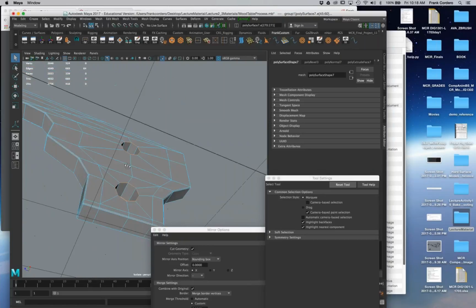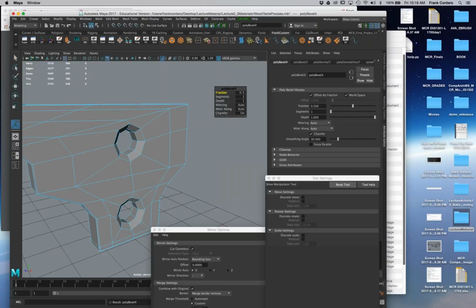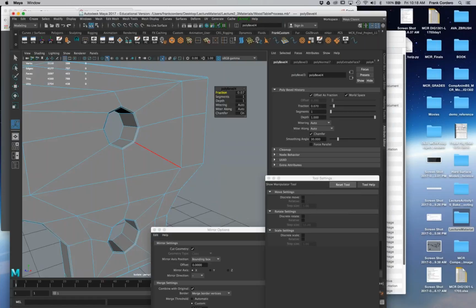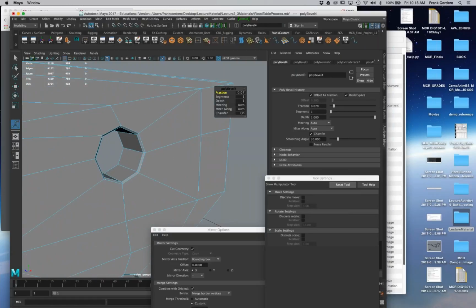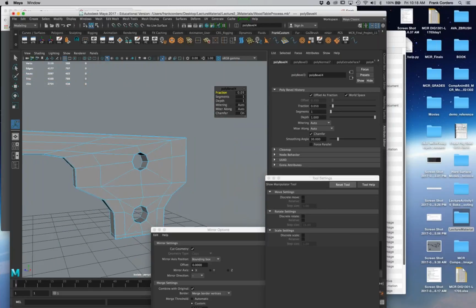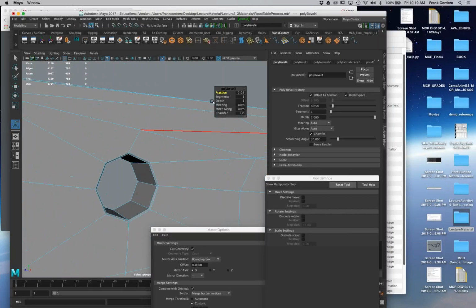So this is a little bit of stuff that I've learned over the years in terms of what I call anticipating the workflow. In other words, I've been working in Maya long enough to know what to expect when I plan my edges a certain way. Maya helps me fill in the rest with what I call a shorthand version of modeling, which is what I've been doing here. And now if I want the resolution for those holes, I'm going to make my bevel a little bit skinnier there.